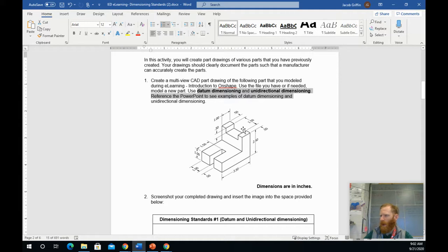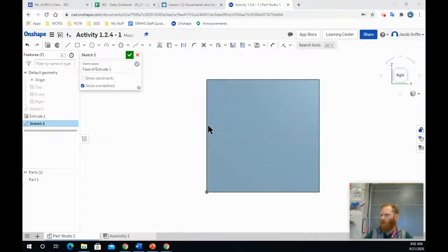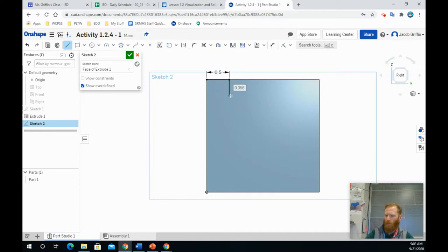And so that cut is a 1/2 inch from the side, so the left or the right side, and then a 1/2 inch down and 1.5 inches wide. All right, so I'm going to take a line, plant it right here at the corner, and go 0.5, and then I'm going to go down 0.5, to the right 1.5, up, and over. All right, so there is my square, or rectangle, and it's 1.5. It's 0.5 from the side, so it should be 0.5 from this side as well.